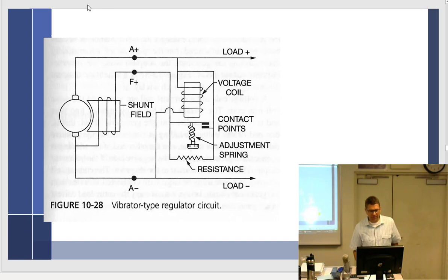Is this an A type or a B type? B type. It's a B type because the field needs what? Is it looking for a positive or is it looking for a ground? Okay, it's looking for a positive. Am I going to find a positive? Can I find a way around through the points? And there's a positive right there. So there's a path right through here.